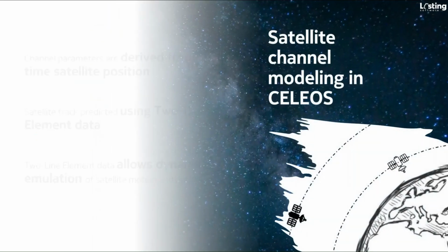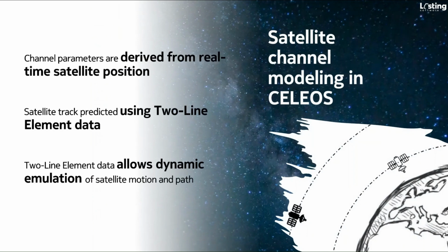CELEOS starts from a realistic satellite motion model. By importing TLE data, we accurately track satellite position over time. This defines the satellite absolute coordinates at each time step, enabling computation of trajectory-dependent channel effects like delay, Doppler, and distance-based attenuation. The dynamic nature of this tracking allows CELEOS to reproduce time-evolving conditions that match what a real NTN terminal would experience.